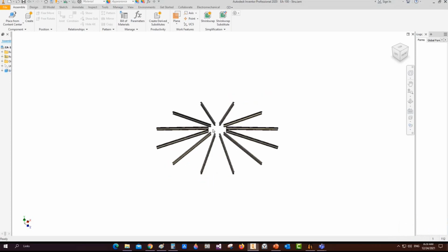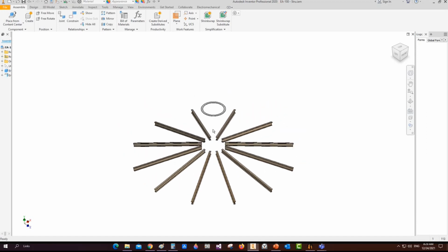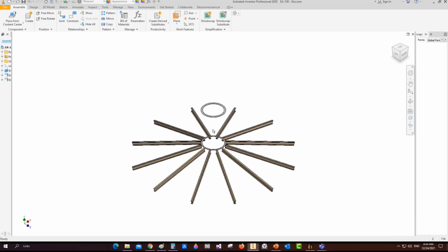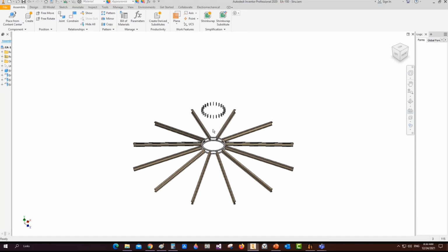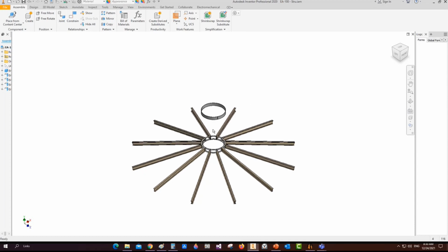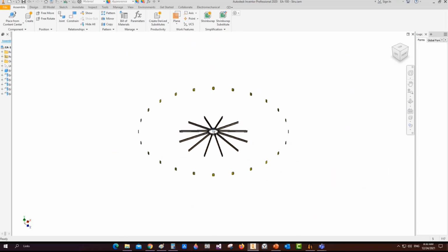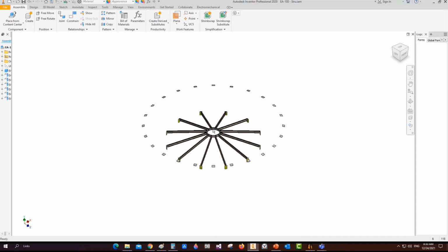So we are dealing with the equipment itself, not the steel structure. The same for the platforms. You can add platforms on SEG, but not in detail. Here I mean the general arrangement of the platform, like location, the start angle, end angle, the rail height, all of that you can define. But you will not get a bill of material for this platform because we generate it as a single part without any deep detail. I'm talking about the steel structure and the platforms.